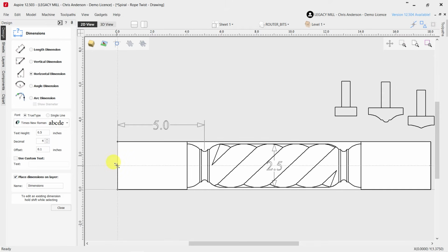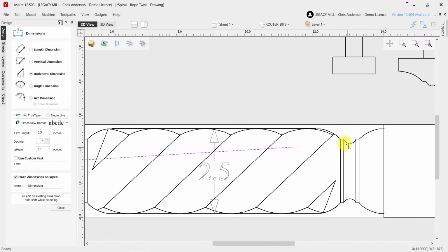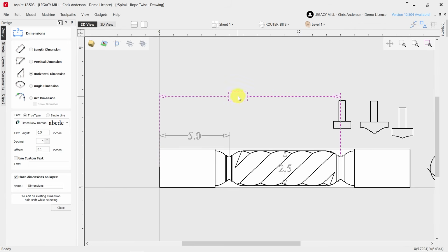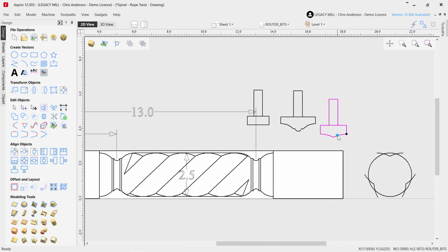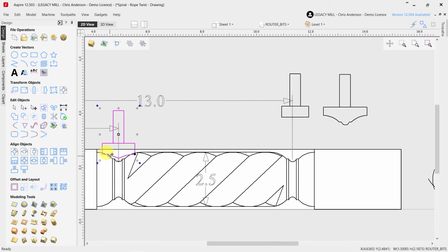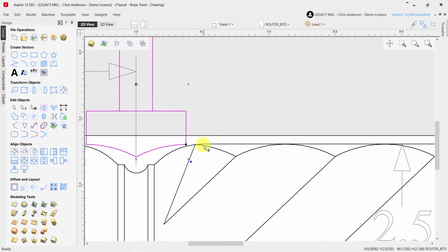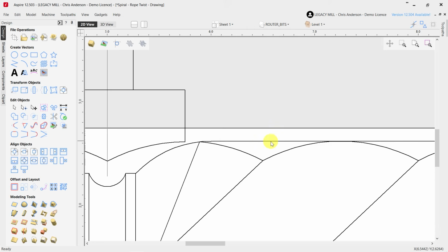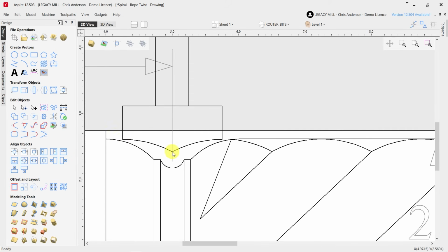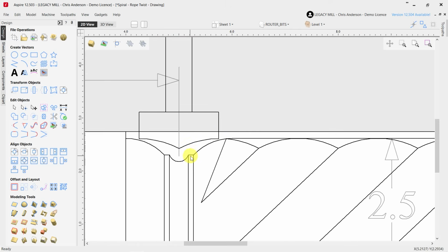And if we go from X0 to the center of this profile, this will be the ending position, okay? So you have your start and ending position. And again, if the cutter were to start there, it won't cause any problems. Okay, so if the tool, again, is positioned here to where the shoulder is going to be at the depth of that 2.5 inches, you can see if it starts here, it's not going to be accidentally removing additional material because this has already been cut away by my larger profile cutter. Okay, so I can start there just fine.